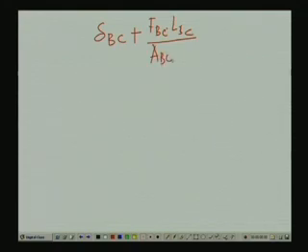So, the equation of compatibility, if we say the expansion of the central bar as delta BC, plus the force in the bar BC times L BC divided by A, the cross sectional area of the bar BC, times E. Since A and E are same, we are writing as A and E. So, that is the deformation of the bar.